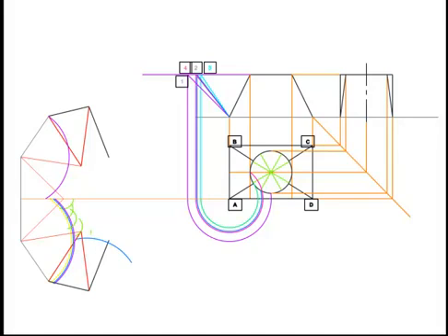We can then do the same process over again. Again, beginning with the blue line, which is got from this true height here and swung from this point here this time. And again, the same distance within these 2 green sectional lines, or this arc, to locate our point.